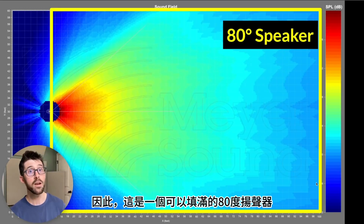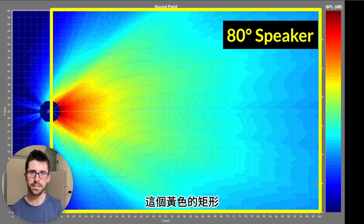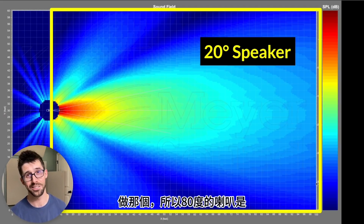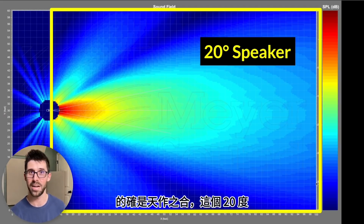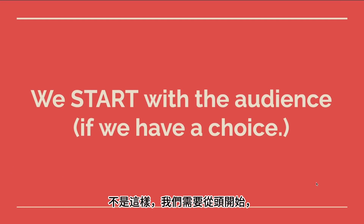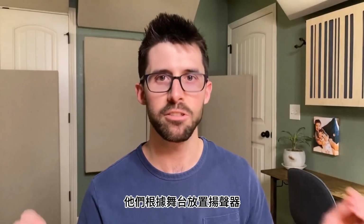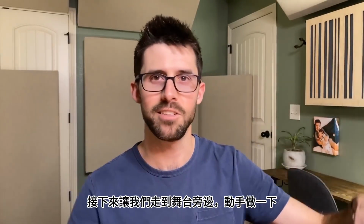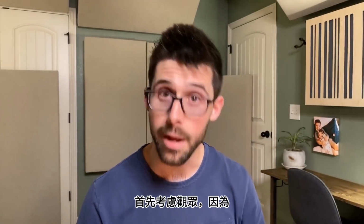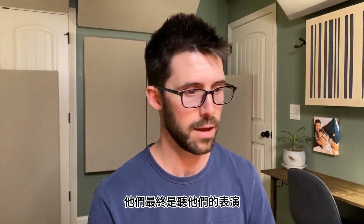So this is an 80-degree speaker filling up the yellow rectangle of this audience size. And this is a 20-degree speaker failing at doing that. So the 80-degree speaker was the match made in heaven. The 20-degree is not. So we need to start with the audience, which goes against the mistake I see everyone making. They usually place their speakers based off the stage. They forget about the audience and just say, okay, I'll put left and right next to the stage. Let's blow and go, have a great show. So we need to start with the audience in mind first, because they're ultimately hearing the show.